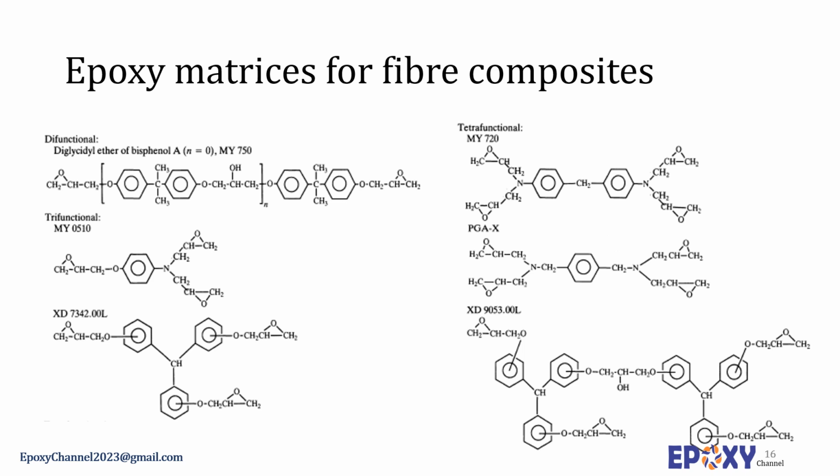The glycidyl ether of bisphenol A with 2 to 4 oxirane rings forms the basis of the general-purpose resins for both adhesives and composites. The glycidyl amines have a higher functionality and potentially high cross-link densities and glass transition temperature and form the basis of the resins for aerospace composites. Typical resins for laminates or composites are presented here.